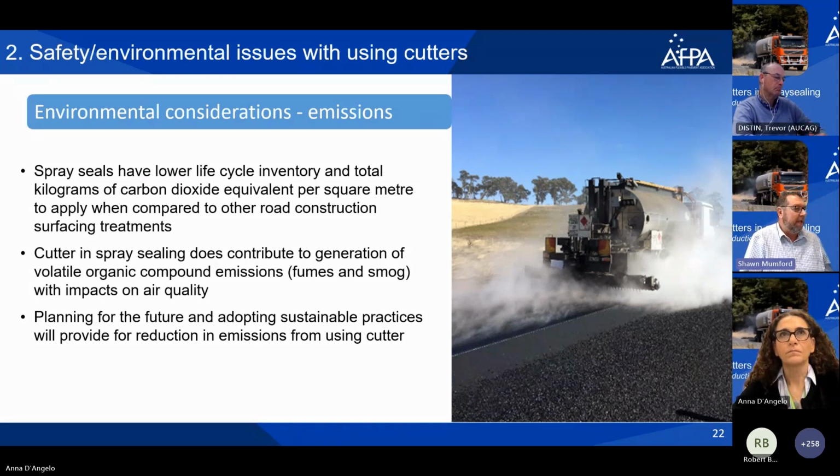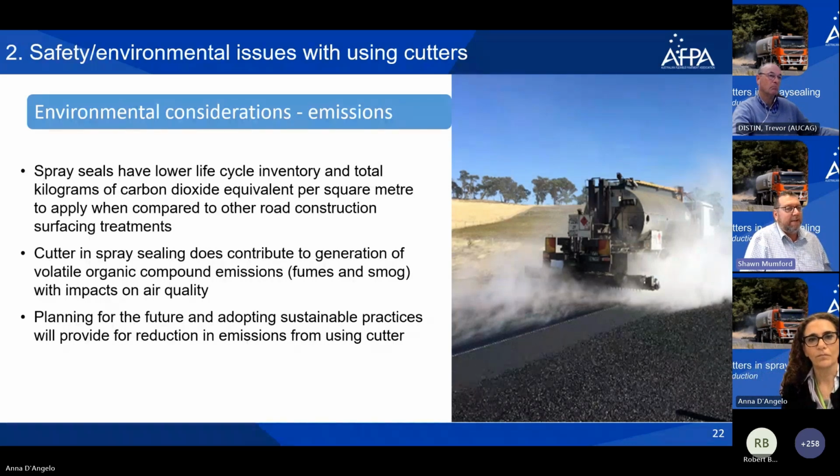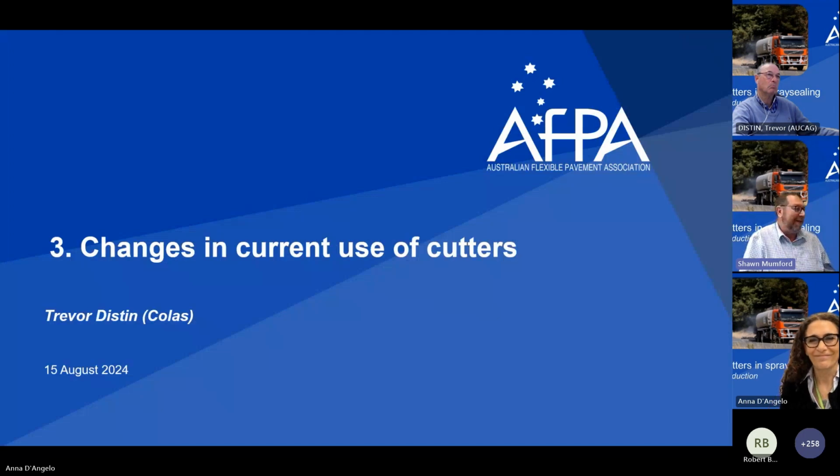So I think just to cap that off, and going back to a couple of the things that Robert said earlier, reducing the amount of cutter through adopting best practices and really having a good understanding of the type of work you're doing, the time of the year that it's being done, and what the outcomes might be in a few months down the track. It's really important for the use of bitumen that you're going to be cutting back with cutter. That's probably the end for me for that part of it.